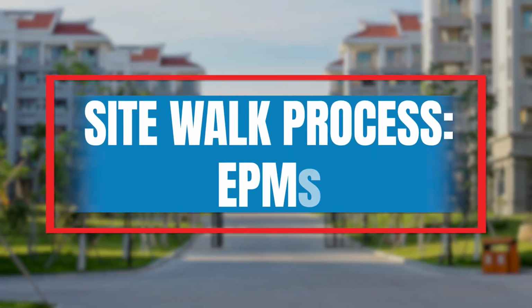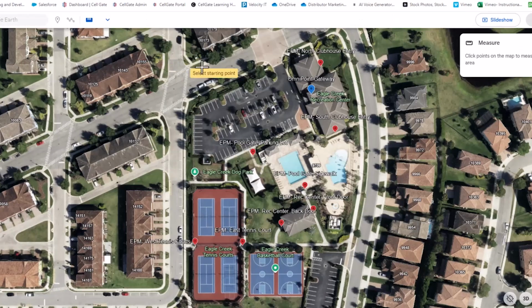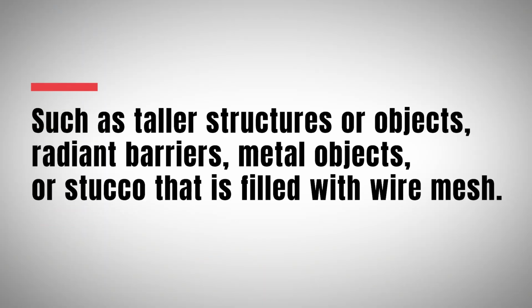Site walk process, EPMs. Now let's focus on the EPMs. Using Google Maps or your measuring wheel, measure the furthest distance from any EPM to the gateway. Identify any obstructions that might hinder EPM to gateway communication, such as taller structures or objects, radiant barriers, metal objects, or stucco that is filled with wire mesh.